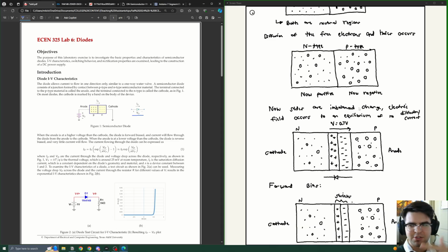And it reaches this sort of cycling equilibrium where the excess charge carriers diffuse. One side is positive, one side is negative, so the electric field makes them drift back to the other side and reach this equilibrium where there's about a 0.7 voltage drop between the two sides, and no current is flowing on average between the two sides. Now that 0.7 is very important. It might sound very familiar, right?